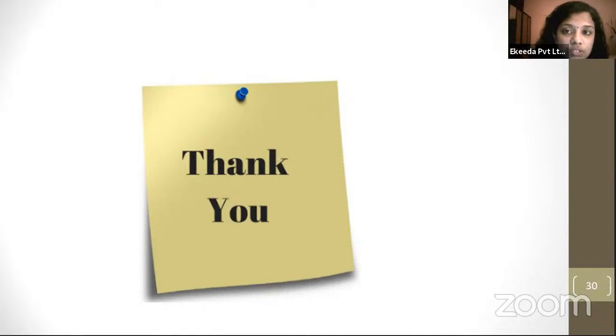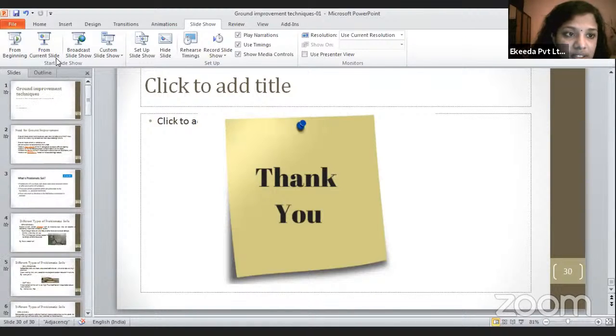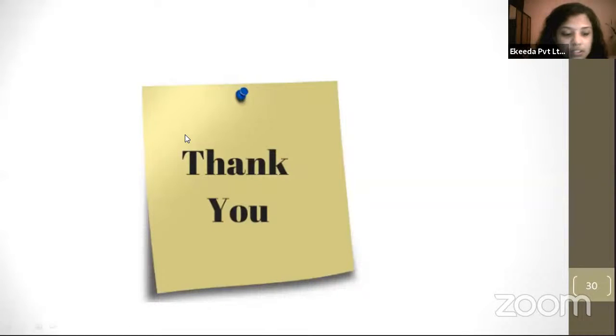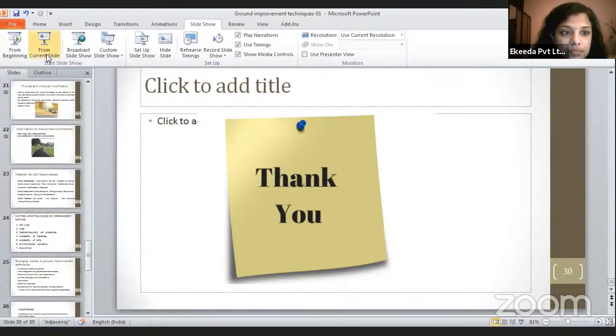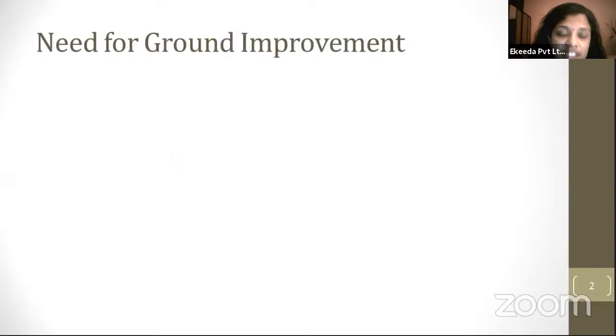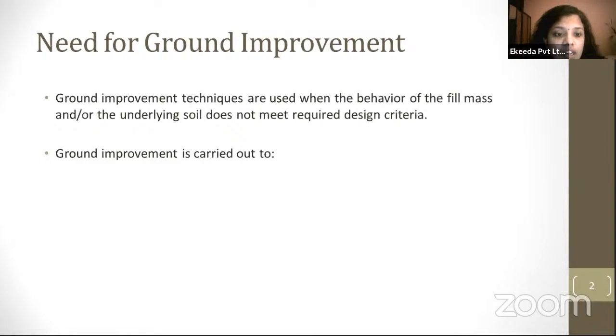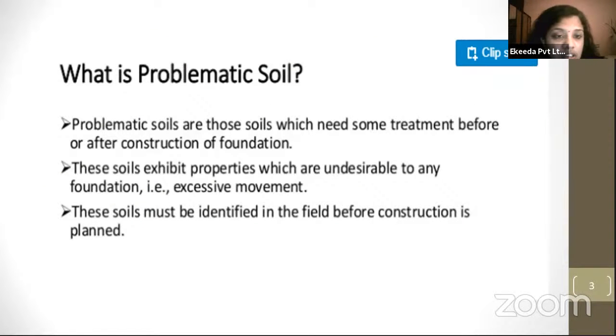So I'll just go through the topics that I have taken. Hope you remember the topics. We discussed the need for ground improvement. It increases the shear strength, the density, and permeability. And we discussed what is problematic soil in a site. Problematic soils are those soils which need treatment before the construction of a foundation.